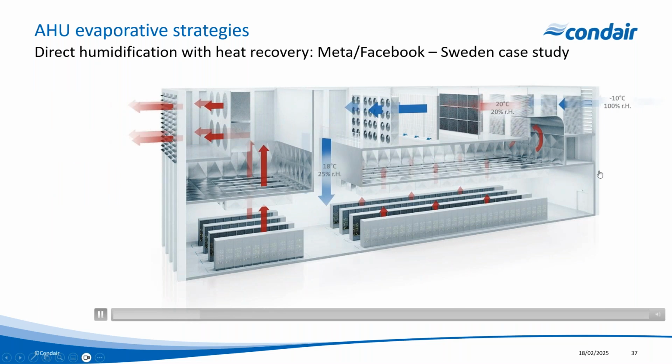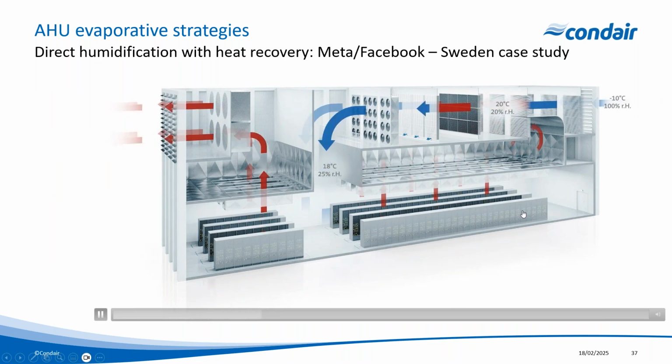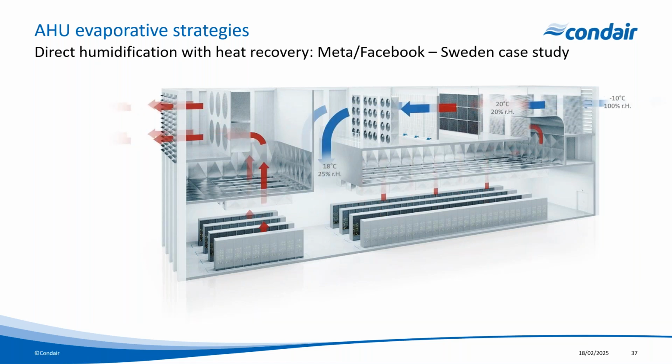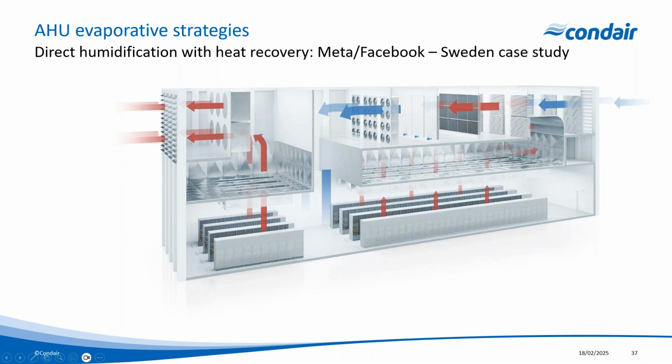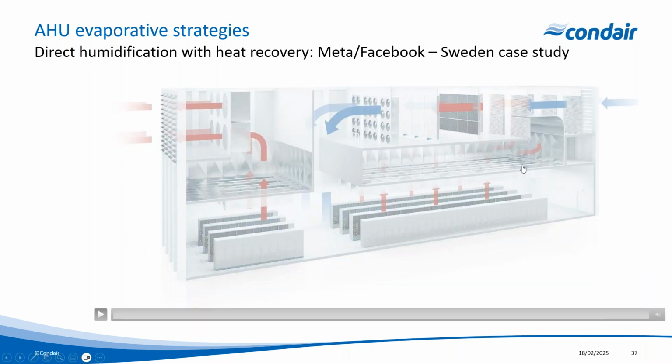Here we can see a schematic of the system, which in this project is referred to as a penthouse ventilation system. Each section is referred to as a lineup, and there were 13 lineups per data hall, with 2 data halls in this building in particular. A lineup consisted of the intake and return air mixing plenums, filter section, the humidifier, the supply fans, the relief fans, and then dedicated controls controlling everything.